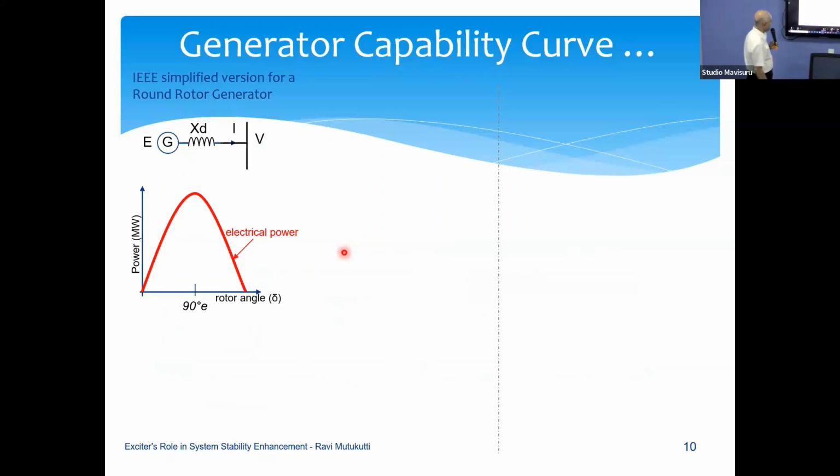If you think about a synchronous generator feeding power into the grid, the impedance between the generator and the grid is assumed to be XD. In this case, I took it as an infinite grid, but actually no grid is infinite. But for the purpose of easing the explanation, you will consider it as infinite, although it is not practical. I already explained that your active power coming from the generator G is in a swing curve, which is E1 V1 sine delta, like that.